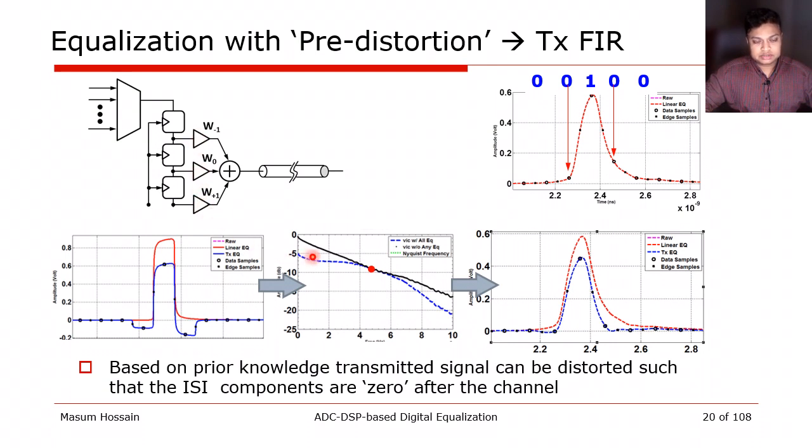From a frequency domain viewpoint, we are effectively flattening the frequency response, but this is done by dropping the DC. This happens because at the transmitter side we are transmit swing limited. Therefore, including the conceptual negative pulse, the peak-to-peak swing has to remain the same.